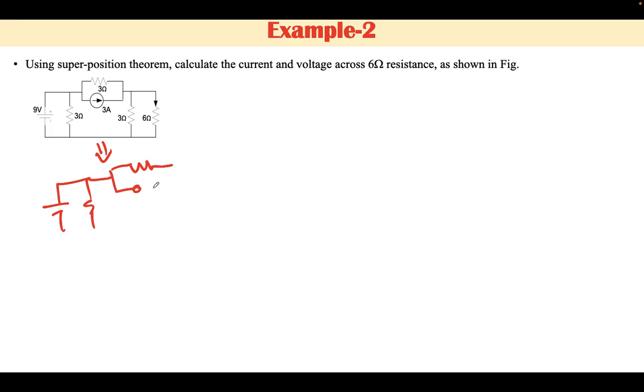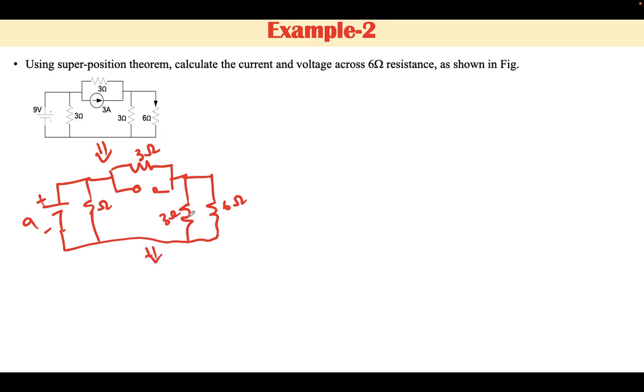resistance. Here we are having a current source, and this current source is replaced with the internal resistance, and the internal resistance of current source is infinity. Now this will be the equivalent network. Now this network can further reduce, these two are in parallel, and the parallel combination can be reduced to